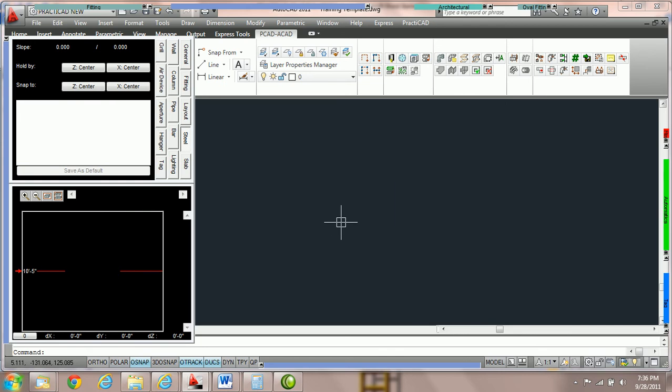Part 4 of the steel tab is working with the Save as Default key. The Save as Default key is the same for steel tab, fitting tab, and every other item in the item box that has a Save as Default button. So this tutorial is going to cover them all. Save as Default, when depressed, simply saves the last parameters of any given entity, so the next time you use it, the parameters are whatever you last inputted.